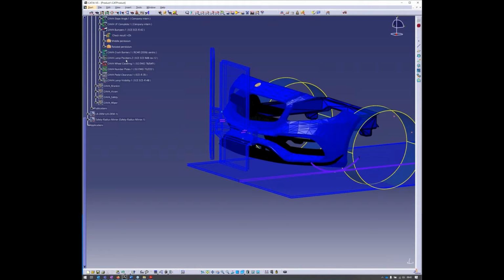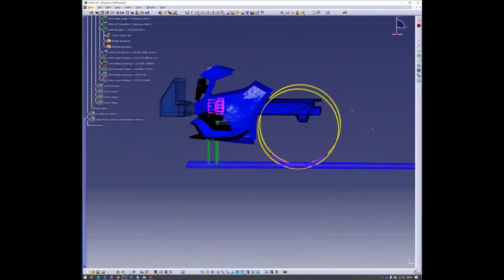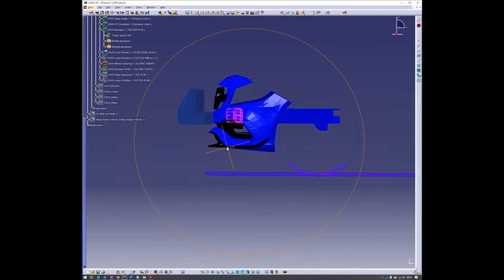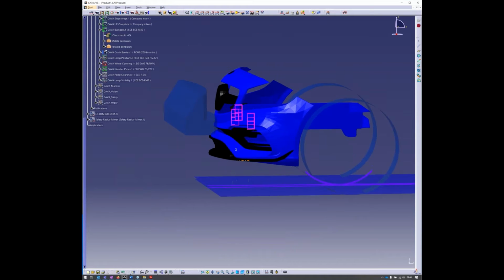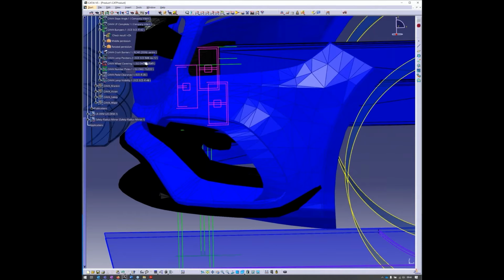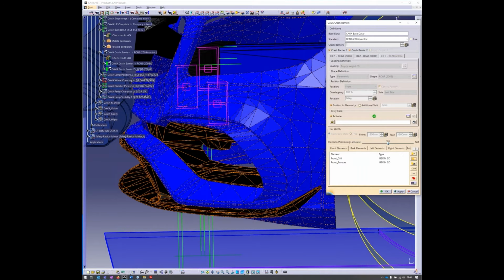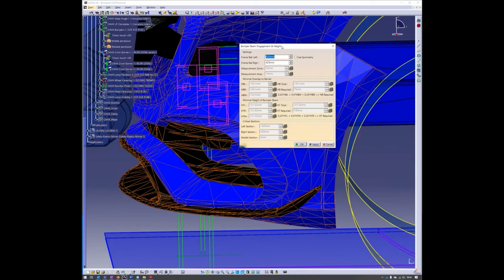Many more crash barriers are available for front, side, and rear impact. I will show one additional one, the classical impactor with the ACR impactor, where CAVA as well provides you with the contact points, with the shape of the impactor, and it will also do an assessment of the overlap values to the bumper beam, which can be calculated with these so-called bumper beam engagement values, which are important for achieving the design goals with respect to the front crash.